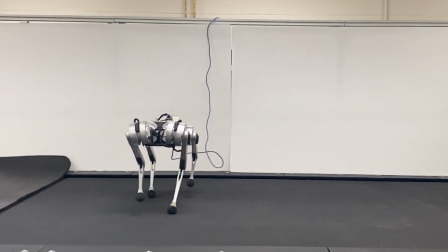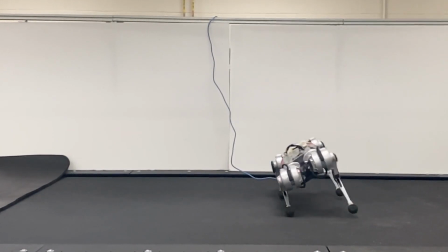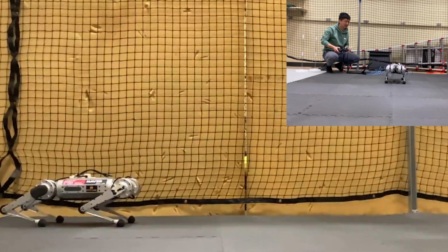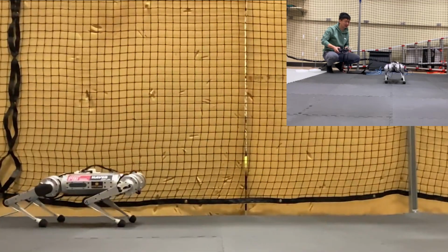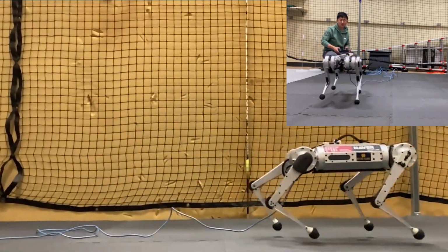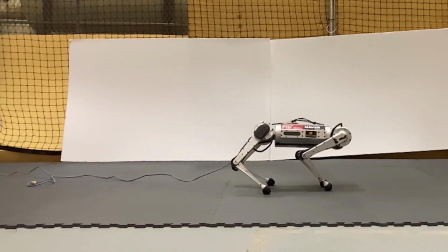For the in-place barrel roll, we generate the barrel roll reference using trajectory optimization offline and connect the in-place trotting reference to it. The same in-place barrel roll reference is then used with a trotting reference and a pacing reference to synthesize a running barrel roll with the associated gaits. The proposed control framework is capable of executing these motions on hardware even though the barrel roll reference is designed for the in-place takeoff.